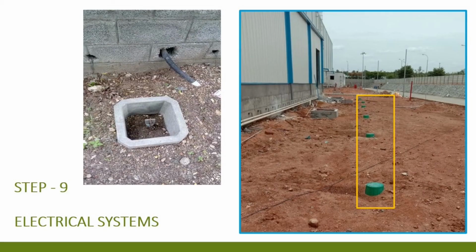Location of earthing pits and the cabling routes needed to be checked for providing earth connections to your server, UPS, workstation UPS and non-UPS power. A separate earth pit and cabling is required for all separate systems.